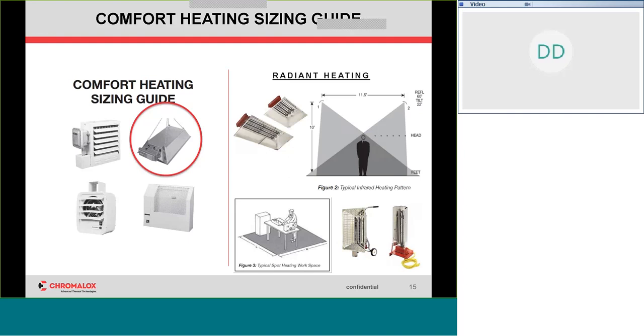So, important safety note. We're always thinking of personal heating. Again, these are comfort heaters. These are radiant heaters. Think of the sun. Think of radiant heat. You're heating surfaces. The standard design for a radiant heater is 8 to 10 feet in the air because the average size of a human is 5 feet. We're using that as the medium. We want to get at least 3 feet or more of separation between the heater and the person.